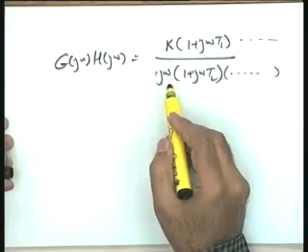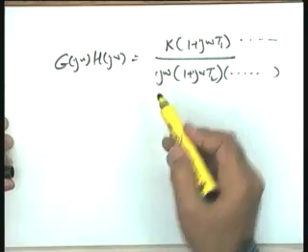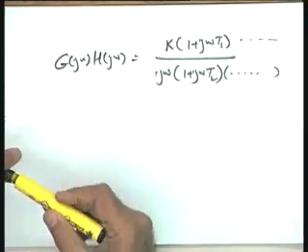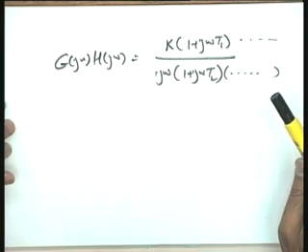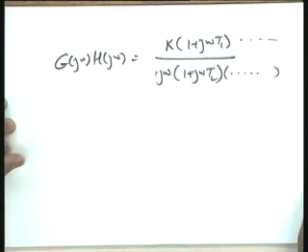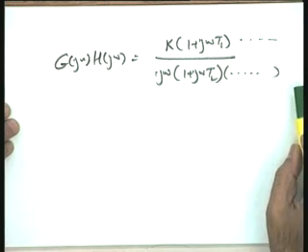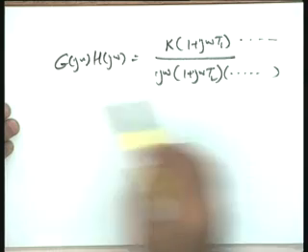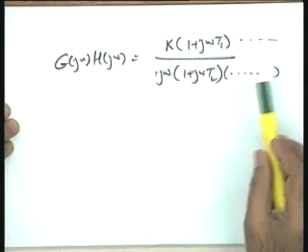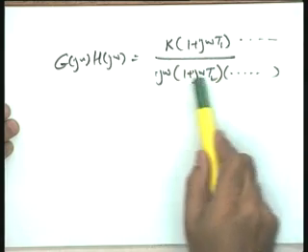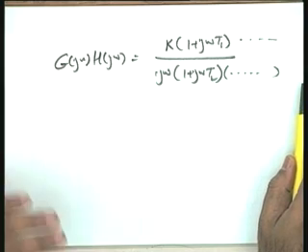Now, you see that I have taken this to be a type 1 system. A square will come if I consider a type 2 system, and so on. In general, it will be an nth power giving you a type n system. So, magnitude and phase is to be calculated, but you see what will happen if I take the log of this particular equation. If I take the log on both sides, these multiplicative terms become additive.